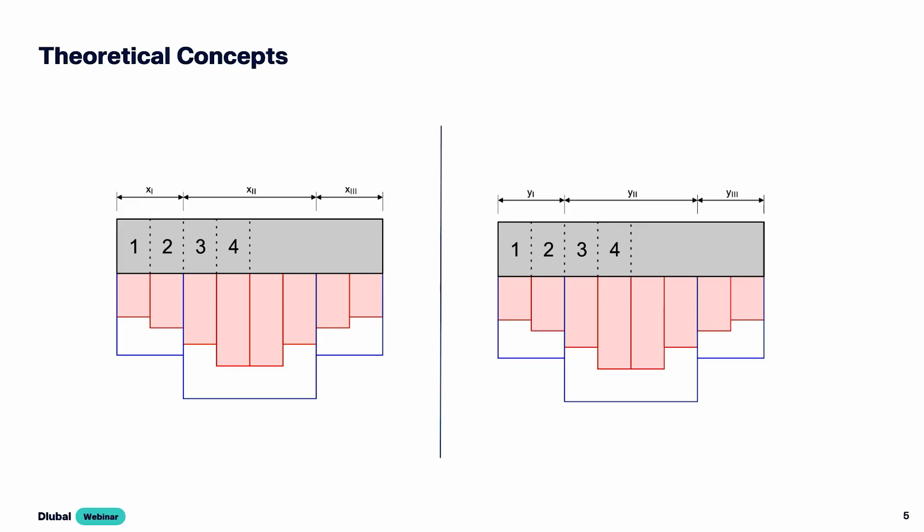The second reinforcement area, x2 and y2, is located in the middle below the column. It covers 50% of the foundation width, perpendicular to the reinforcement direction. The first and third areas are located at the edges, each covering 25%. And these 3 reinforcement areas are the values that are entered in the plate reinforcement tab.